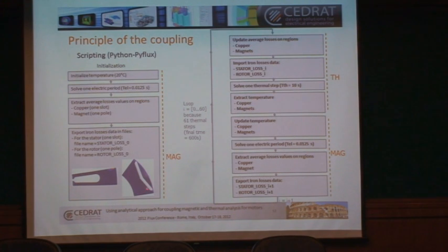And then in the air gap, I touched it very quickly. What we make sure is that whatever temperature, this is doing convection inside the air gap, so it's heating the ambient temperature, and we make sure that whatever energy comes out of this by convection is the same as the energy that comes out of here. So we adjust this to make sure it's the same. So if one has more, what we're going to do is inject a little energy because it would actually travel through the air gap.